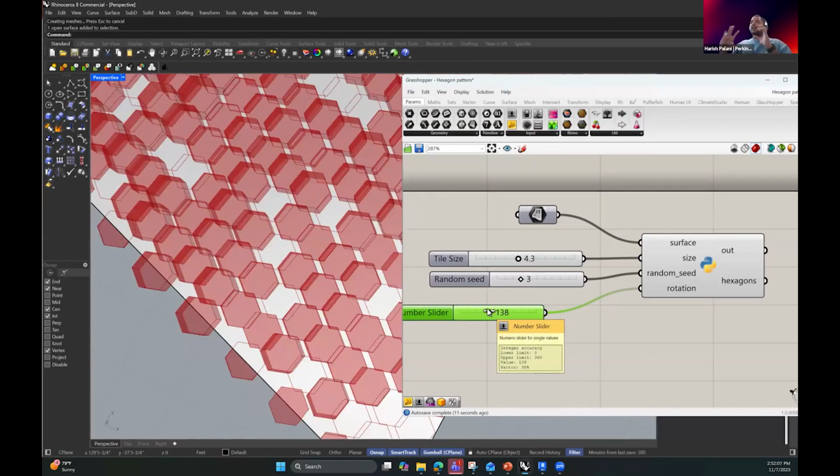Maybe we should specify, if I need a little more variation in it, make a 3D rotation. So you can specify, if you're a Rhino user, you know all the commands. So there's a 3D rotation. You can add a 3D rotation value to this. And then now you can add an input and output and just make it into a Grasshopper player and use that as a Rhino command.